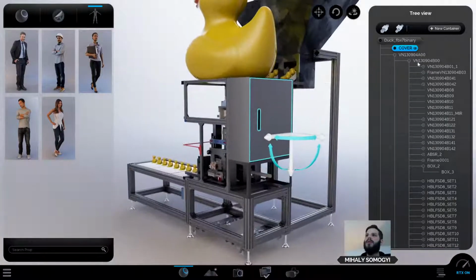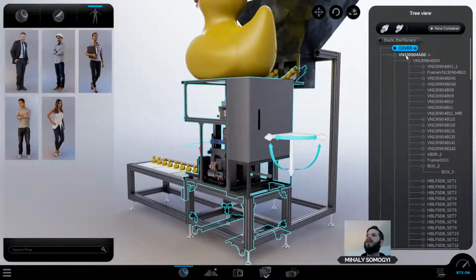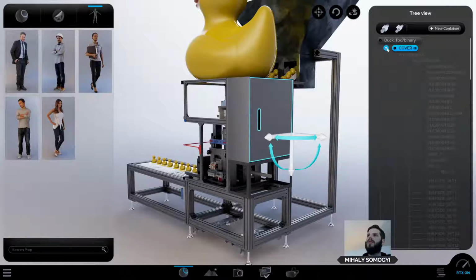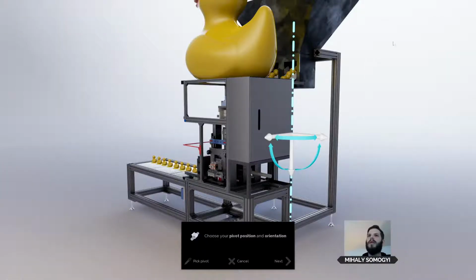Once I convert an object to child, you will see the name changing into this rounded container that becomes blue once it's selected. So once you have something like this, you can select your constraints. Up here you have 2 of them, and you can drag and drop it. You will see that a small blue dot appears on the left side of the name, and that's where I'm going to drop it.